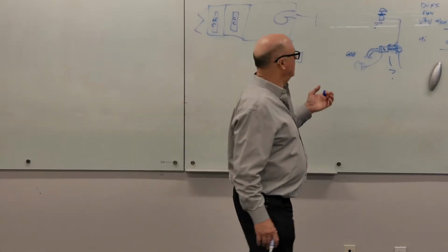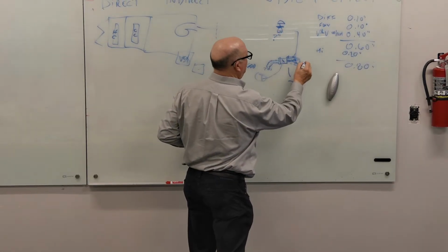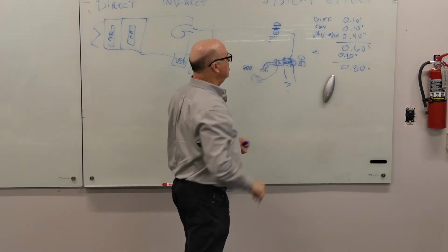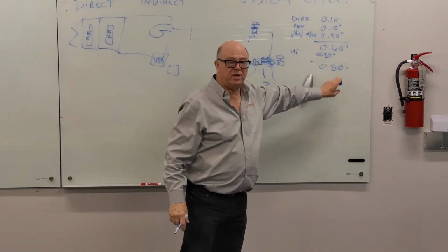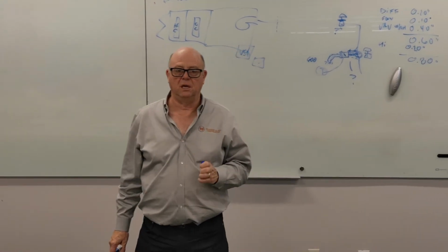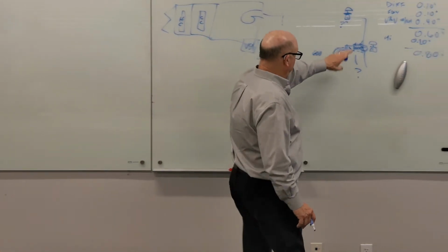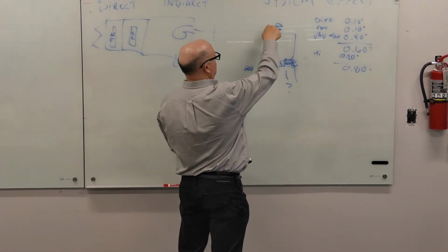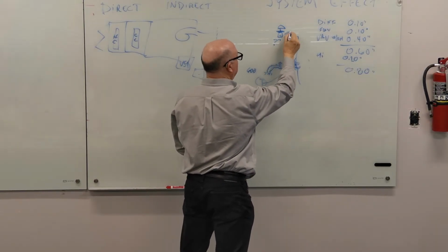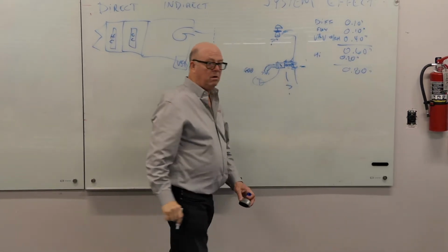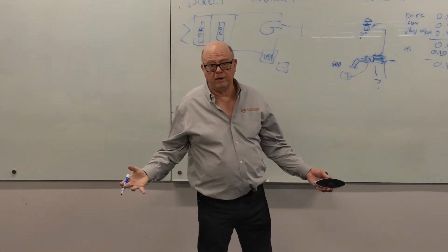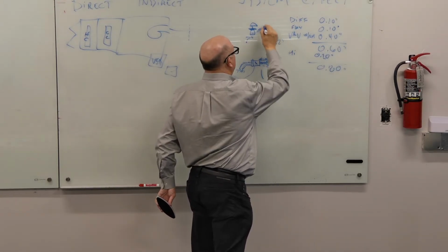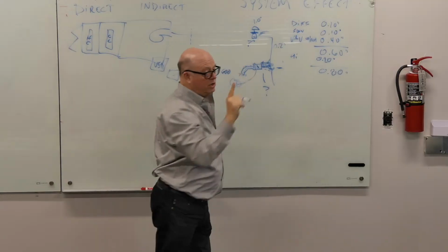Now, where are we going to put this? If we put it right here, then based on what I got here, it's 8/10 of an inch. Like I said, that's low. It should be a little higher than that. But if this is out near the end of the run, and we've just put this 2/3 of the way, well now we've got to also measure the pressure differential between there and here and add that, right? So maybe that's 2/10. And so maybe this is 1.0 inches, which is still low.